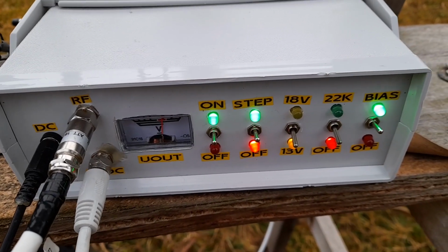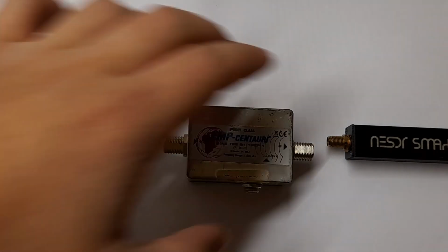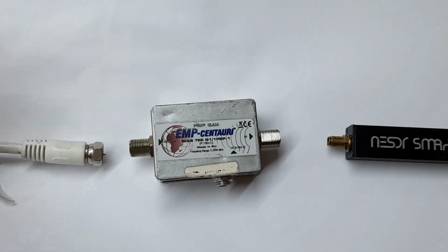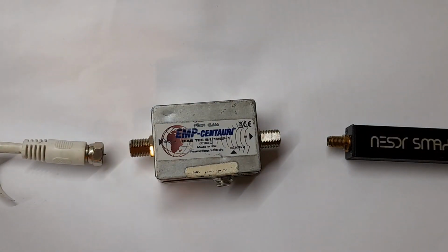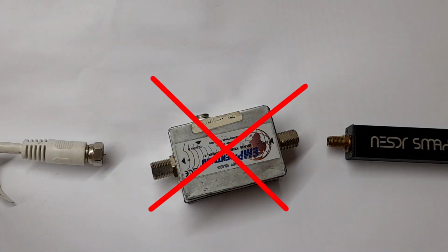Be very careful when connecting any direct current supply to a setup with an SDR. The RF only connector of the bias T has a capacitor which blocks any direct current from entering and subsequently damaging the receiver, so you can safely power the LNB at these voltages, but it will not protect you if you connect the bias T in reverse, which is a mistake that can happen easily.